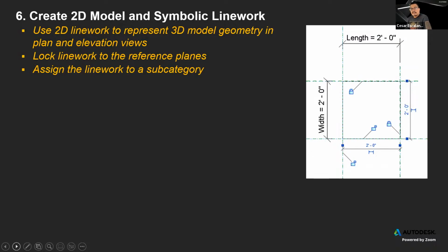If you are preparing, for example, desk layouts in a floor plan, maybe you don't need to add 3-dimensional families, and you can do your studies more efficiently with less impact on the performance using a 2-dimensional family. And a 2-dimensional family is just a flat line that represents an object.